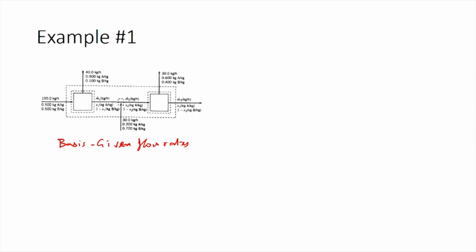Why do we want to start with the overall system? If you look at the different systems, the overall system has only one unknown stream, which is M3. You do not know the mass and the composition of the product 3 stream. All the other streams crossing the system boundary are known. So, we could start with the overall system. Let us start with this and perform these calculations.